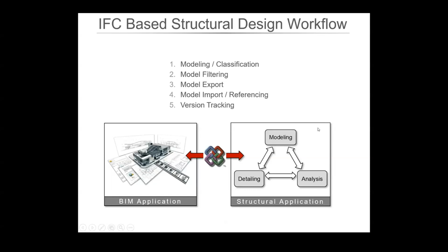You can tell it that it's a wall or a slab or a roof or covering or whatever. So always just keep an eye on those sorts of things so that they can be accurate. And again, there are things that could be done either directly out in the object, or you can create schedules to go and check that all your elements are being classified properly, or all the relevant information is being put in the right place.